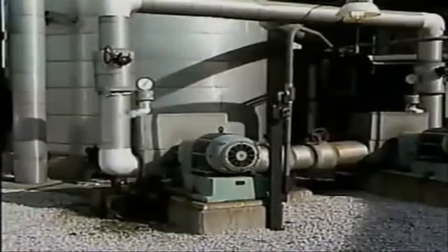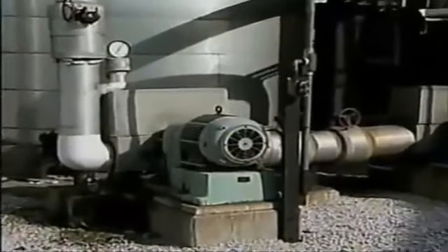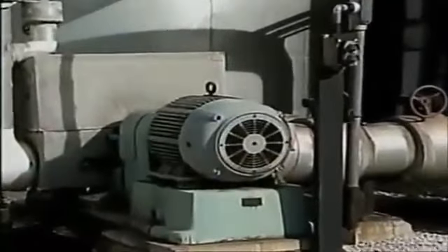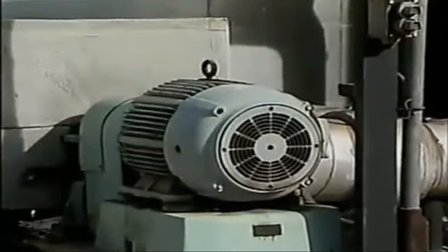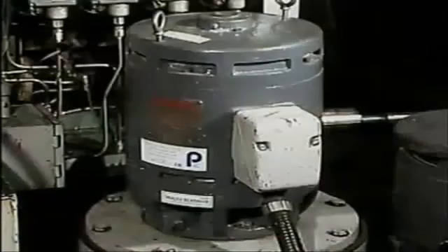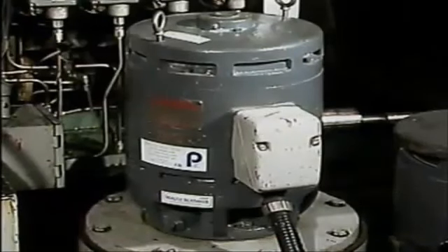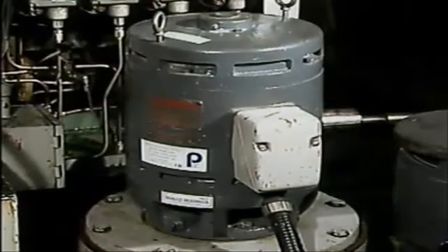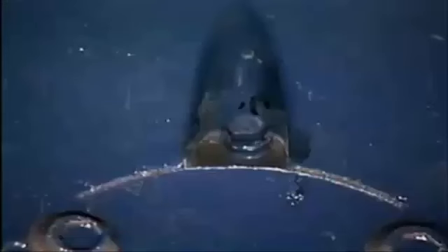For proper operation, bearings must be kept lubricated. Lubrication reduces friction between the bearing's parts. There are some motors that use sealed bearings that do not have to be relubricated for the life of the motor. The bearings of some other motors are greased through grease fittings as part of a regular maintenance schedule.